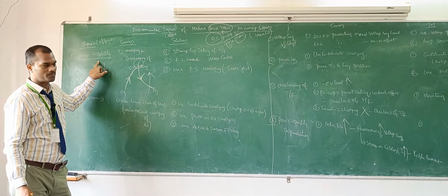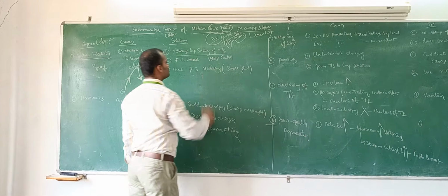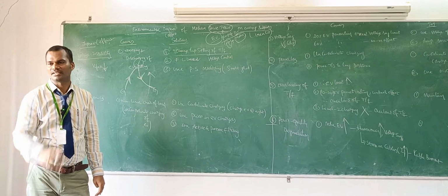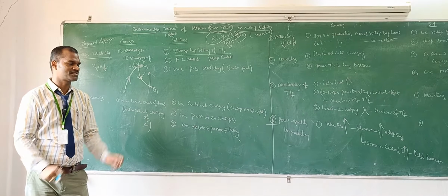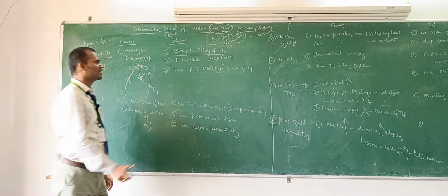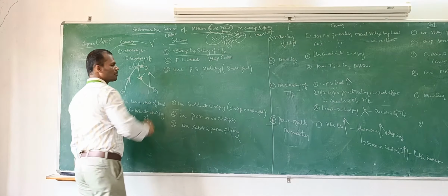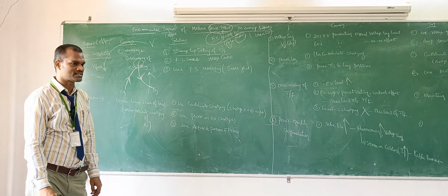existing power system. So the solution is to have an automatic tap changer or manual tap changing setting, continuously made at the substation level. Substation people should adjust that tap setting or tap changer to maintain a proper voltage of 230 volts or 415 volts for single phase as well as 3 phase.